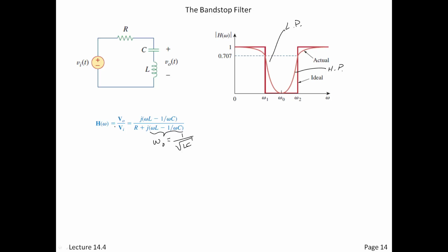So at real low frequencies, you have the capacitor dominating. Then at higher frequencies, you've got the inductor dominating. This term is large, and this term will be large. It will head toward 1. It's the in-between time that makes the transition, as you go from what's your definition of low and high, and this is your definition of low and high.